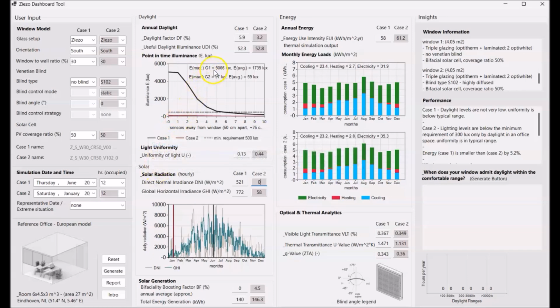The higher levels of light in the unshaded window can be explained by and correlated with the highest solar radiation profiles on that day, as shown in the radiation plot. Meanwhile, the lower levels of illuminance admitted through the shaded window in January are correlated with lower solar radiations. This is due to a fully overcast sky blocking direct sunlight, leading to reducing indoor light to fall below the lighting minimum requirement of 500 lux in an office room.